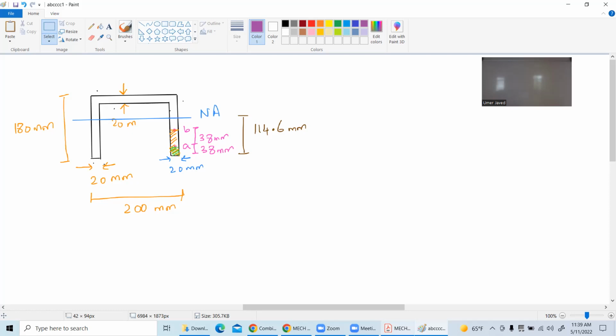Let me explain it like this, because this becomes a little confusing many times. If this is the bob, and this is your theta in the positive sense, you divide this into its components. This is my mg, as you drew, and this is your theta. Then this is the mg sine theta, as you said. Then you do summation of moment about the point of rotation equal to I alpha, which is equal to I theta double dot. We will talk about I later. Then you can see you will have a clockwise moment, because this is opposite to your positive sense of theta: minus mg sine of theta into, as you said, the moment arm, which is the L.